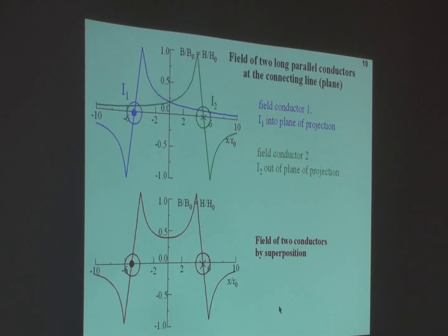now we calculate the flux between the conductors, and then we get phi. Then we say U is n d phi dt, and then we will get U is L di dt. And so we can calculate this inductance.